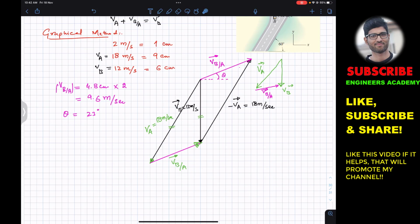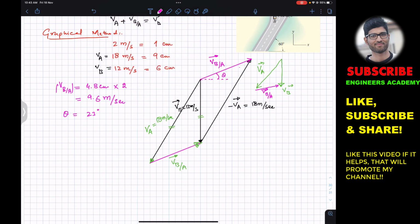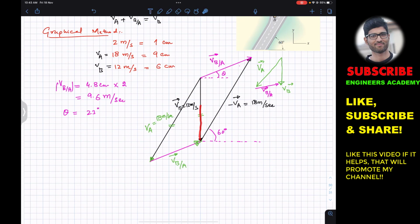So if you want to find this VBA magnitude using the cosines law, if I draw a horizontal line here, this VA vector is making 60 degrees, and this VB vector is vertical, so this is 90 degrees. So 90 minus 60, this angle is 30. So let me write that this angle is 30.